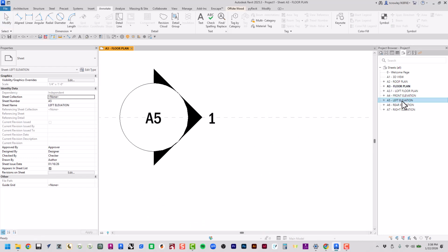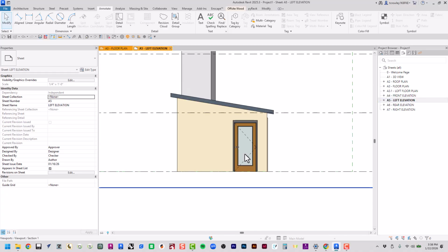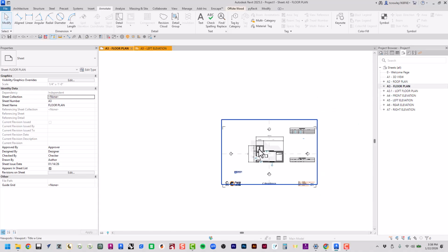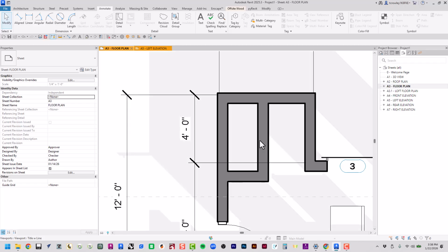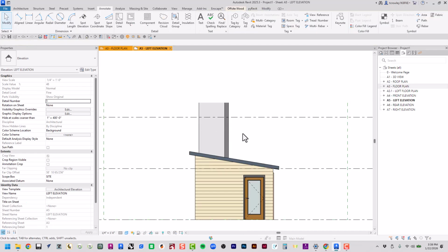Let's look at this in 3D. I'm going to click this little icon here, default 3D view. And if you don't see your model, go ahead and double click on the middle wheel button, and it should zoom to its full extent. Unless something's hidden here. Oh, there it is. You can also use this view cube, and it'll reorient you.